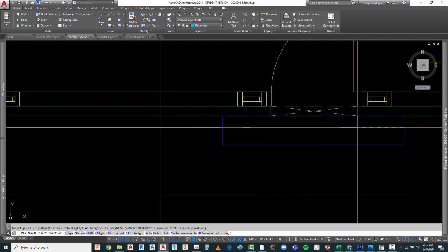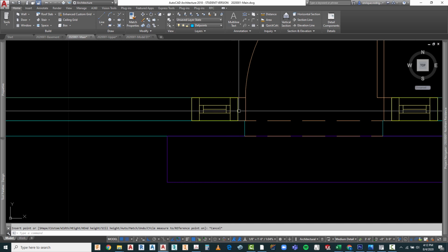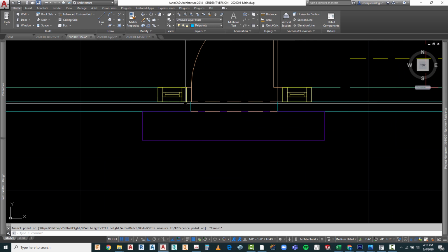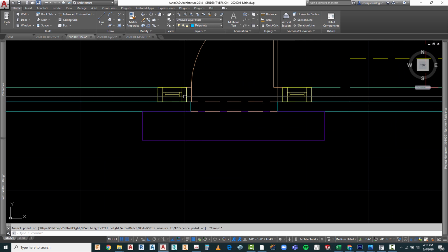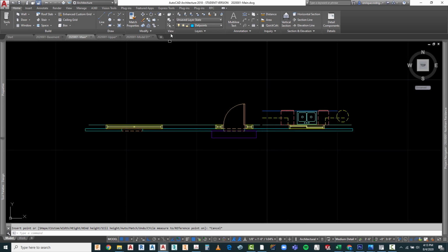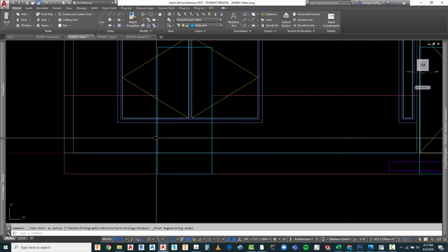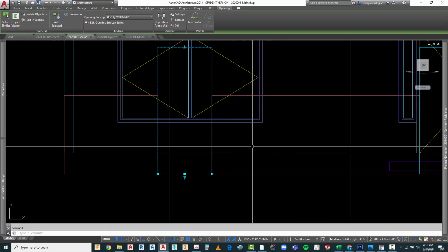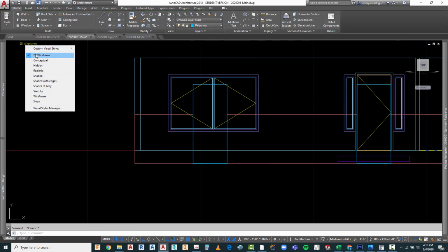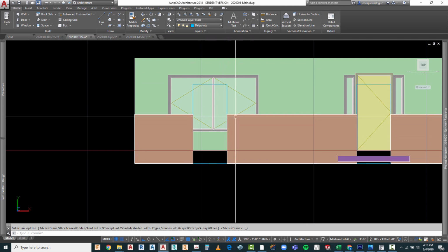And I'm just going to do one in here, because the way that I designed this, I made sure that the window jamb and the window frame and the door frame were flush to each other. So there is no small gap in between those that we would have difficulty figuring out what to finish it with. So let's see what that looks like from the front now. If I go to the front, this line right in here represents our opening. So once again, if you take a look at conceptual, we've already begun to cut this out, but there's modifications that we need to do to that.